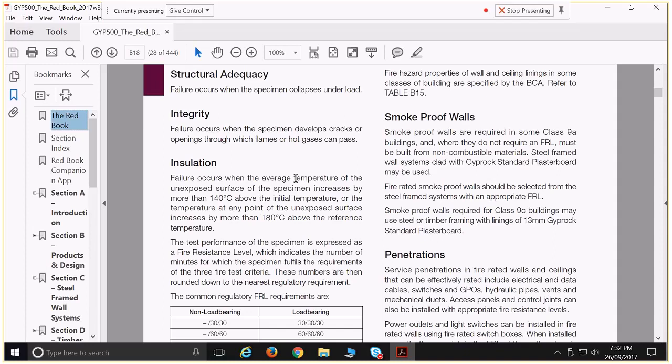For a brick wall, they've got their own rating. You can use Hebel as your cladding wall, then timber on the outside. That's another way of doing it. The Hebel provides you the FRL you need. It's a good way of doing it. So then you don't need your fire check or that. Yes, it's just different.